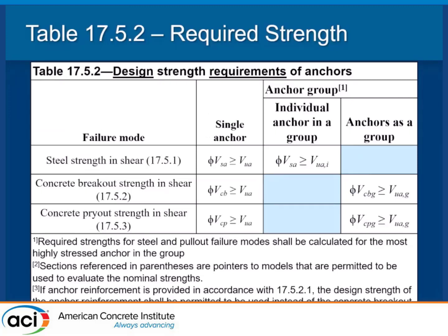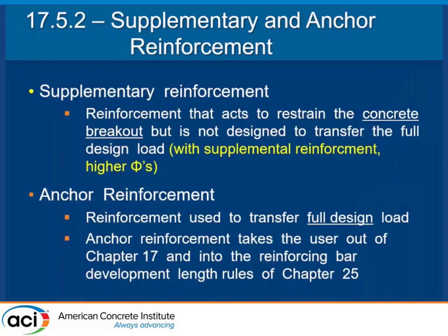We're well over 20 years of using the CCD method. It was incredibly painful for the first at least 7 years, introducing it to the community. Anyone who had to live through it will tell you it was very difficult. I think we've largely worked through all the problems with the original anchors, but now we're trying to slowly introduce all these other different types of anchors, which I said earlier are not included.